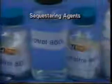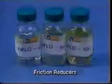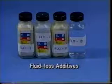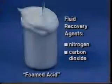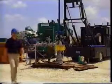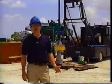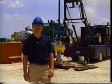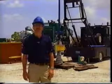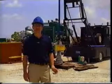Other common additives include sequestering agents, clay stabilizers, bacteria control agents, friction reducers, fluid loss additives, and fluid recovery agents such as nitrogen or carbon dioxide. There are no universal additives for solving formation acidizing problems. Therefore, both field results and lab tests should be utilized for optimum results. The engineer must decide on the most cost-effective treatment design after considering all the available data and treatment options.